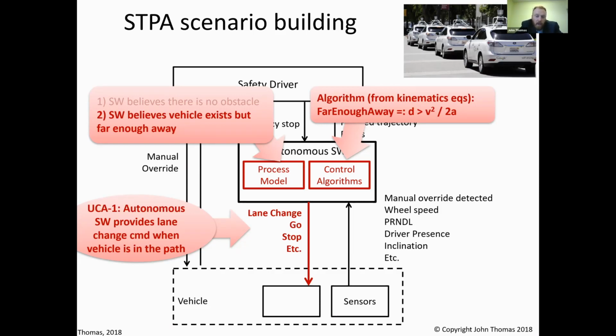What it comes back to is different ways to specify it in terms of time or distance, safety margin, or whatever. But one way to define it is an assumption about the acceleration of the other car, not the current acceleration. Let's say the current acceleration is 0. It's a constant velocity. It may be okay to cut in front. It's your assumption about what they're going to do when you cut over. You assume that they're going to decelerate by some amount, and you're going to be okay. So, to be technical, it's relative acceleration because you're going to be accelerating as well.